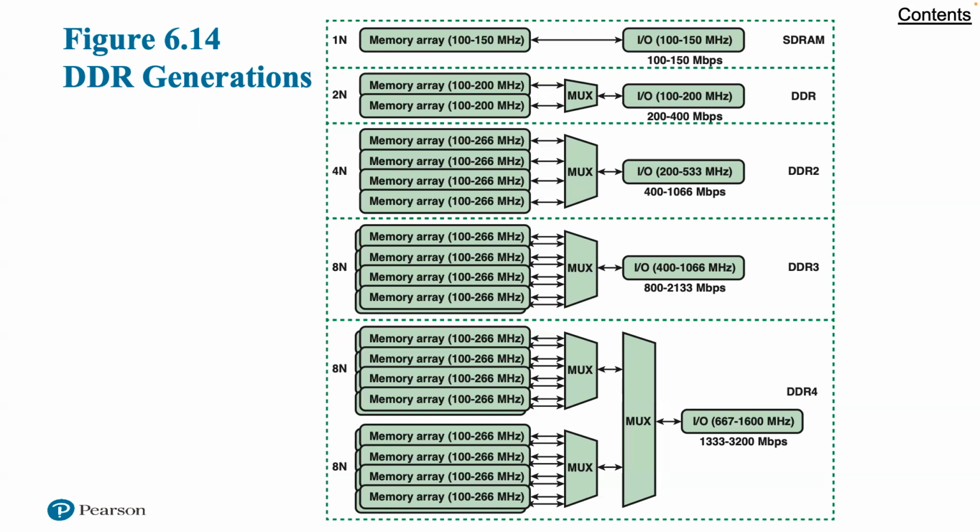And then the downside is the prefetch. It effectively determines the minimum burst length for the SDRAM. For example, it is very difficult to have an efficient burst length of 4 words with DDR3 prefetch of 8 words. Accordingly, the JEDEC designers chose not to increase the buffer size to 16 bits for DDR4, but rather to introduce the concept of a bank group.